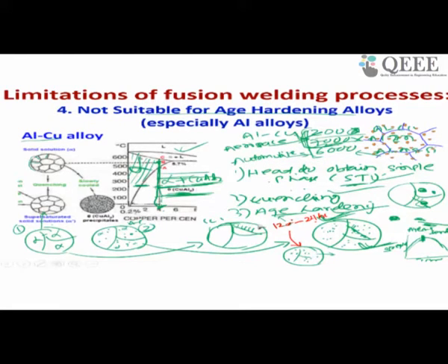Now, with this microstructure, when you do welding, what will happen? In the heat affected zone or anywhere, because of the temperature, we want 120 degrees for 24 hours. They have done that and supplied. Now in welding, what will happen? In the fusion zone, it disturbs this precipitate. At high temperature, this precipitate will again dissolve in the matrix.